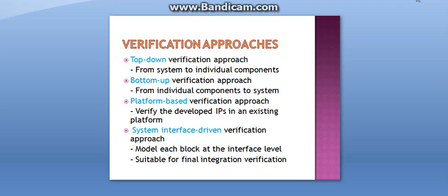Second is the bottom-up verification approach. It is from individual components to system. It contains some level testing like component, block, and unit level testing, memory map, internal, interconnect level testing, system level testing, etc. Next is the platform-based SoC verification approach. It verifies newly developed IPs in an existing platform, and interconnect verification between the SoC platform and newly added IPs.